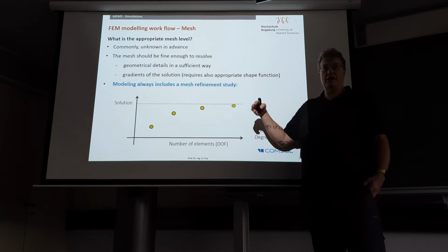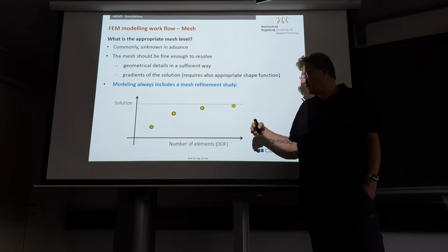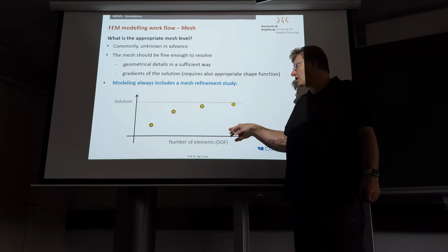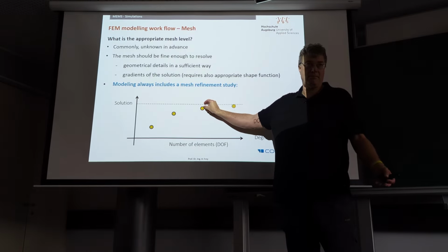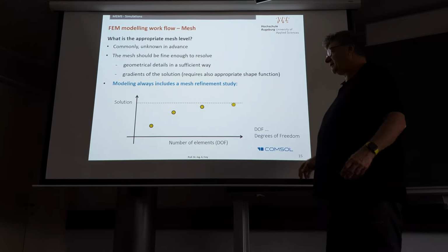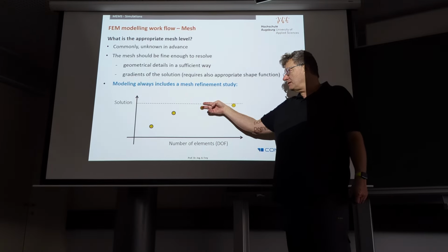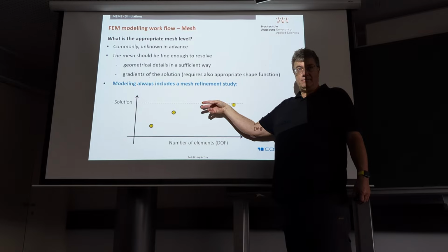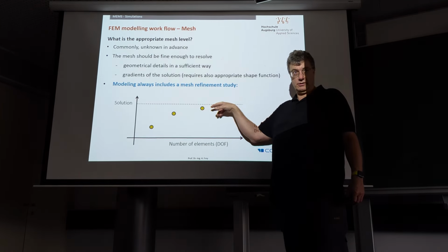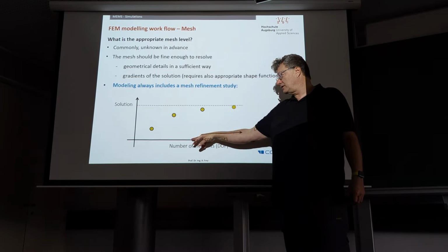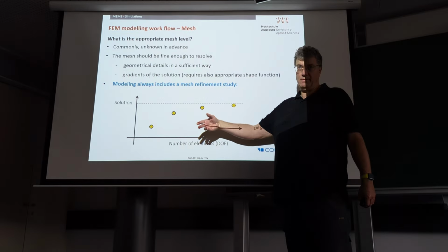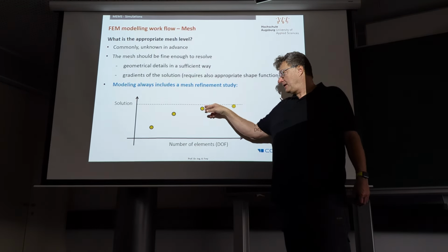And then it's a matter, again, of engineering judgment if you decide for that number of elements or if you go here. Obviously, here you have some mesh dependency, but this, again, you have to evaluate for every single simulation if this is important or not. You have many sources of possible errors. This is one. If you make the mesh only that good, then you could make the solution better by going to a finer mesh, but you have to pay with memory, you have to pay with calculation time.